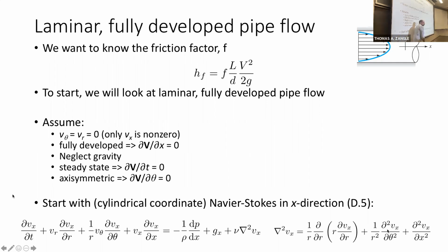This is our pressure term. One thing I want to draw your attention to here is that we have this total derivative, this dp/dx. We're using a different derivative indication here for dp/dx. This is not the partial derivative of pressure with respect to x. Pressure is only varying in the x direction. And despite the fact that we are fully developed, the pressure does vary down the length of the pipe. That's the main reason why we're using a different derivative symbol here. So fully developed means the velocity profile is unchanging down the pipe, but the pressure can vary down the pipe.